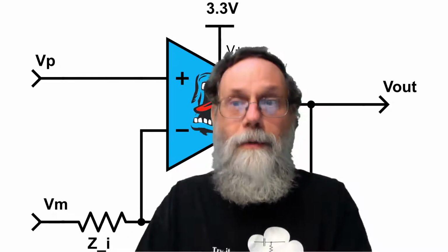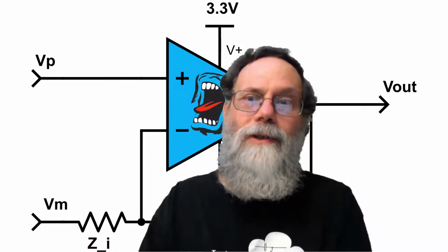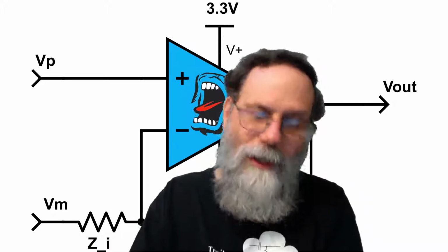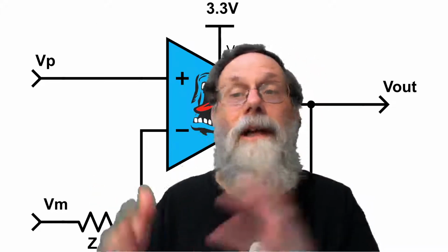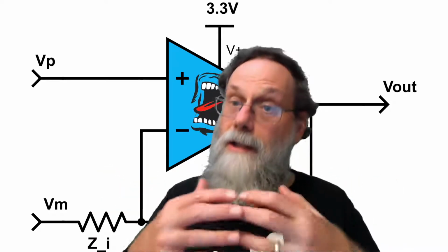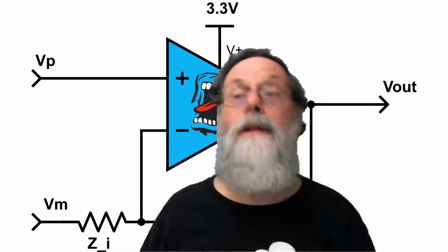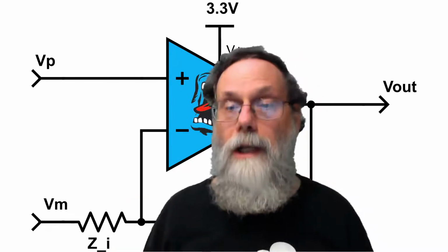Let's look in more detail at this point. Oh, there's a loose wire. Oh, I computed this resistor wrong. That's supposed to be 22 kiloohms, not 220 kiloohms. That sort of narrowing down things and then double checking your expectations versus your observations is really a large part of what debugging is about.